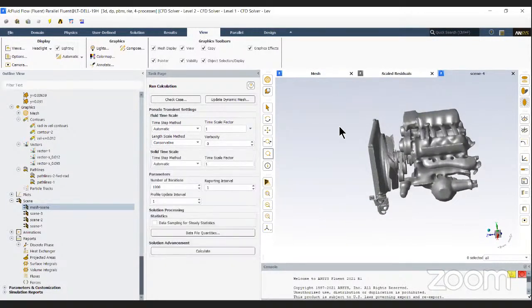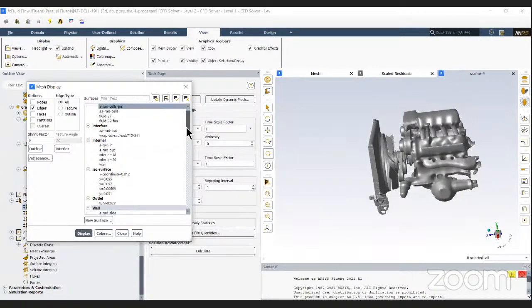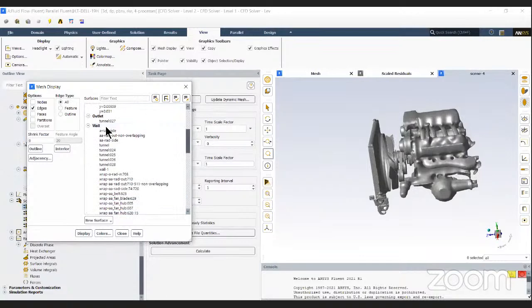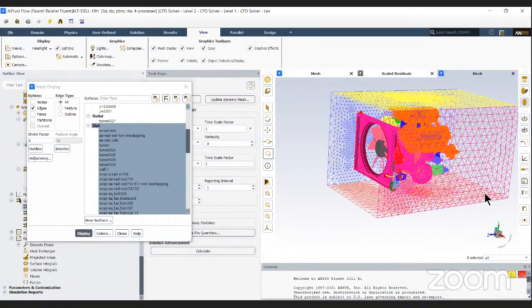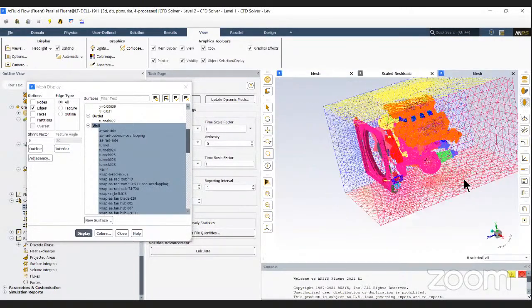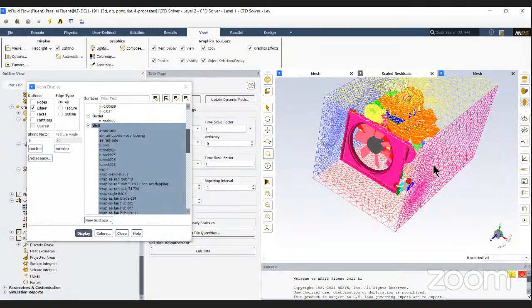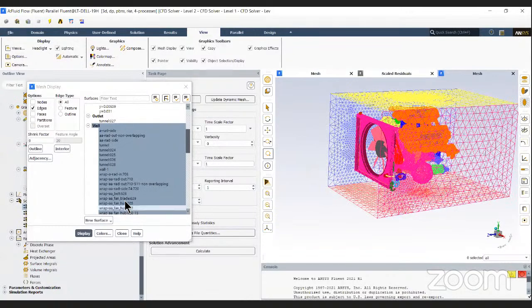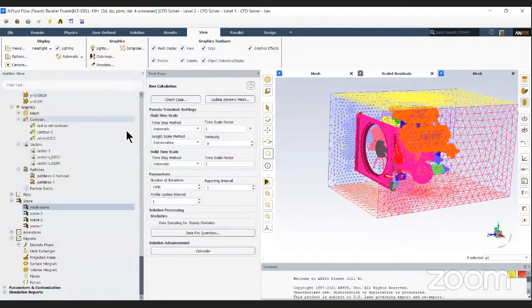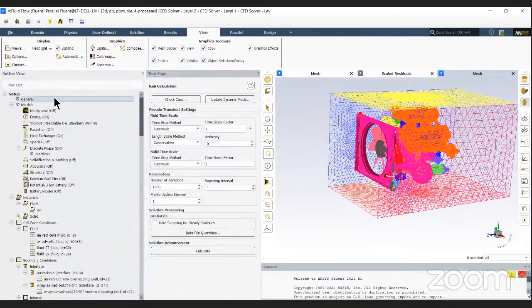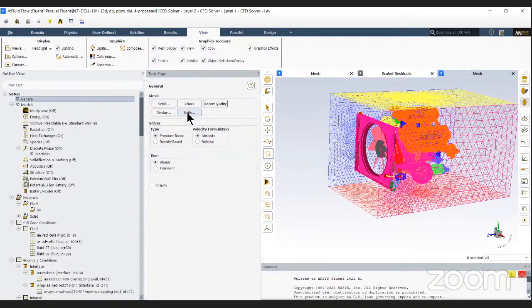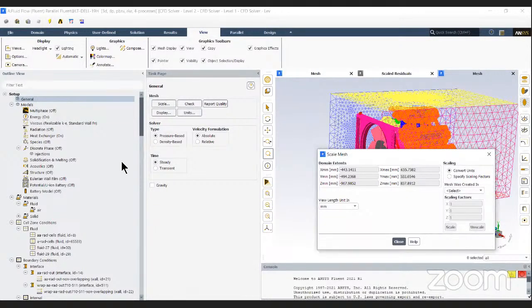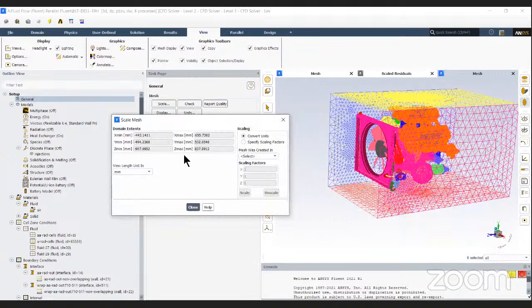Now this entire assembly is encompassed within a tunnel. So if I were to show you everything, you'll see that this has basically walls on all its sides, and then this front face is open to the atmosphere at 0 gauge, right? So when I start setting up the simulation, the first thing that I do is I input my mesh and then I look at my scale, okay, to make sure that my domain extent is selected correctly.